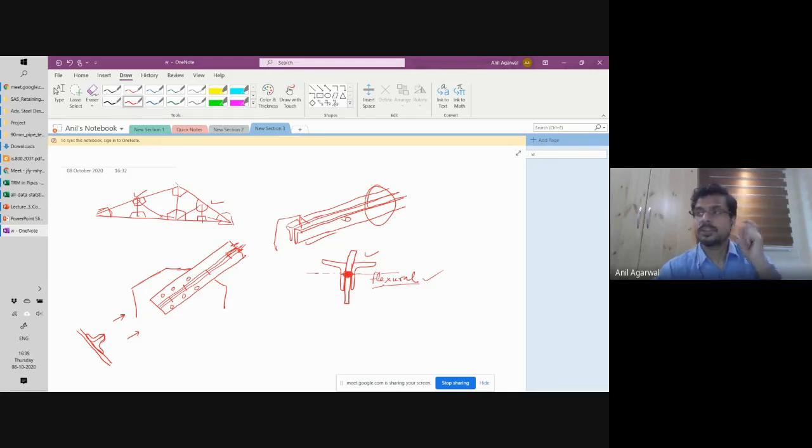Fine. So one thing you do is you change the mode of buckling. The second thing that you do is, because they are both combined now, the net I value, moment of inertia, or r value, will be not only twice as high, but much higher than what was available for a single angle. So I or r, moment of inertia or the radius of gyration, increases multifold, not just twice.